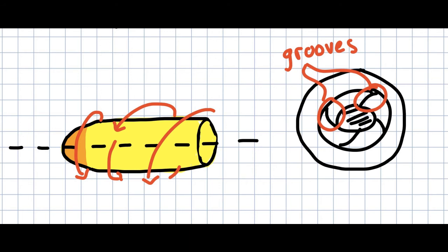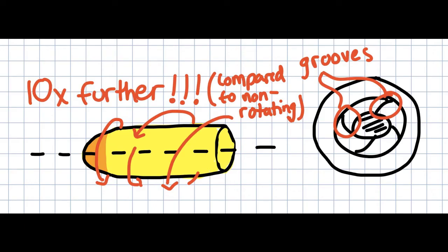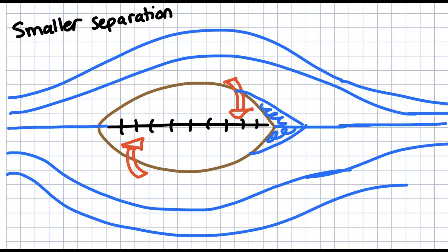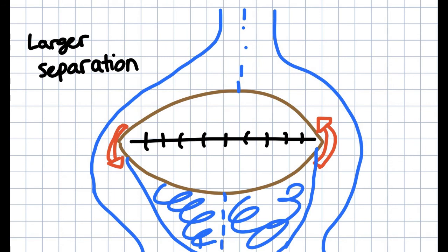Rifles and barrel rifling involves a groove along the inner part of a gun barrel to give the projectile, a bullet, a spin about its major axis upon exit, stabilizing it. Similarly, if we look at the diagram, a thrown football or a spiral also has a spin about its major axis that causes a stable rotation and less separation of the fluid off of the back end. On the other hand, a kicked football often rotates about an unstable axis, where more separation off the backside leads to a higher drag force from the fluid.